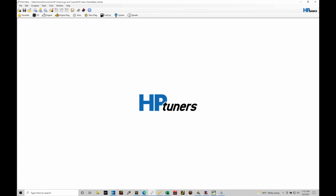Okay, so let's get started. We're going to be taking a look at understanding our dynamic airflow parameter in our GM Gen 5 applications. The dynamic airflow is an essential channel that has to be calculated right, because fuel, spark timing, and torque calculations hinge upon that reading. We have two different airflow modes operating at the same time in our GM Gen 5s: mass airflow and speed density.